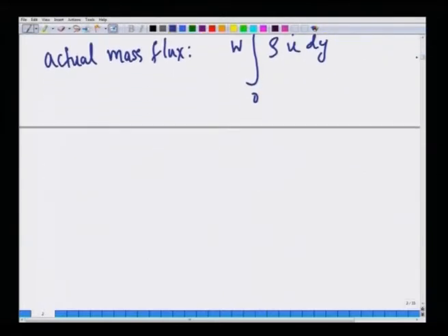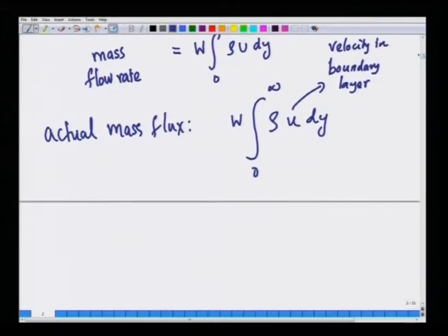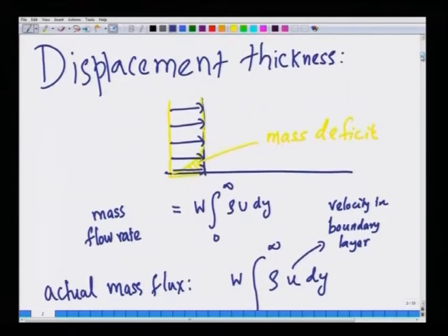Okay. So, now the way in which we envisage or define the displacement thickness. Essentially the net effect of the boundary layer is almost like lifting the plate to some distance, so that after this distance the flow is uniform, and the actual flow rate, which is obtained by integrating this curve, is obtained by simply taking U times this distance.